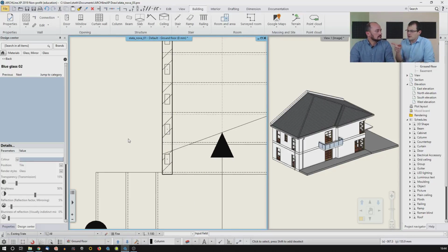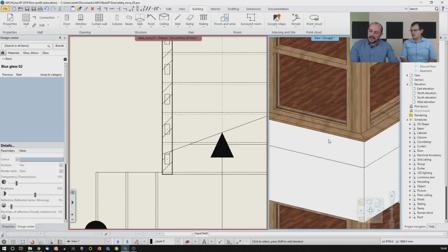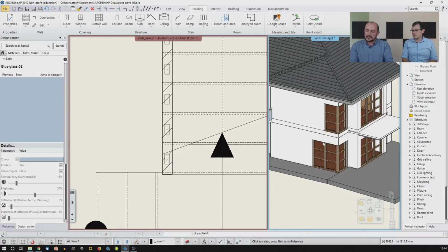can we actually move inside the model so that we can see what's going on? That's right. I understand it will be difficult because we are in axonometric, but what can we do? In case of an axonometric, however close you zoom, you won't ever get into the model, because that's why we call this an axonometric. You need to go into perspective.